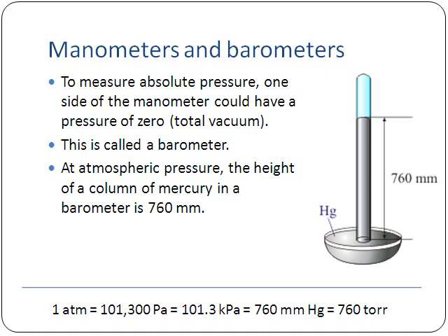What we have on our barometer is a glass tube. The glass tube stretches down and sits in a pool of mercury. Up in the top glass part of the barometer, the pressure is 0. No pressure at all out here. On the outside, there is air pressure that's going to push down on this mercury that sits in the pool. That air pressure will force the column of mercury to go up, and so I'll have a level that'll sit somewhere right up here. And so this is how I have set up my barometer.